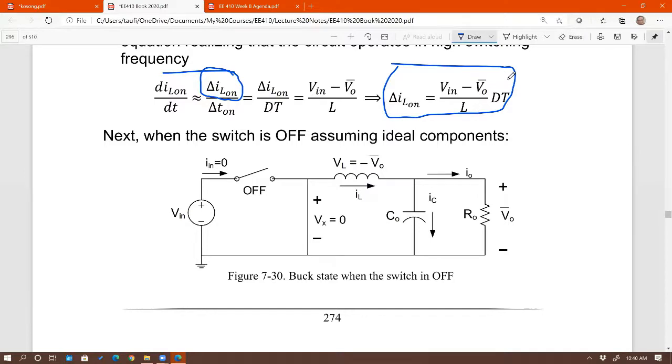When you determine the voltage across the inductor, you have to go back to the reference. Reference is plus here, minus here. So to be consistent, right? So you can see that the voltage across the inductor at this point is, well, this is pulled to the ground. So I know this is going to be 0. And here is V out right there. That is V out with respect to ground. So you can clearly see that the voltage across the inductor is going to be minus V out. Any question on that one?